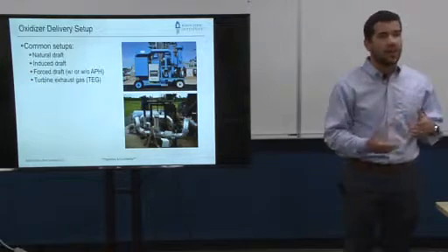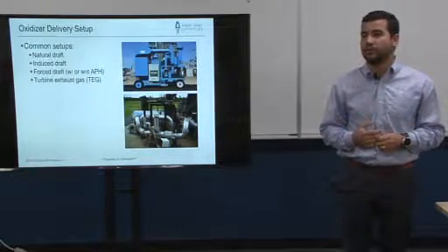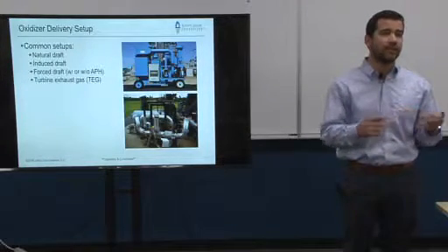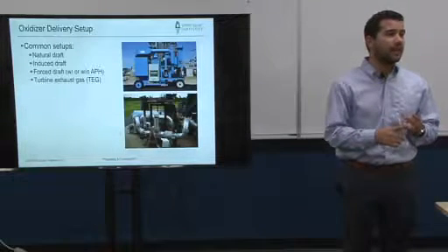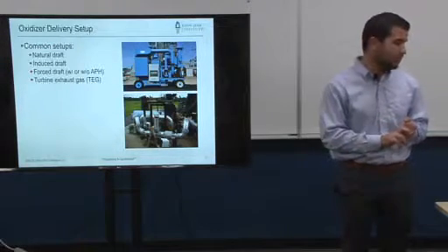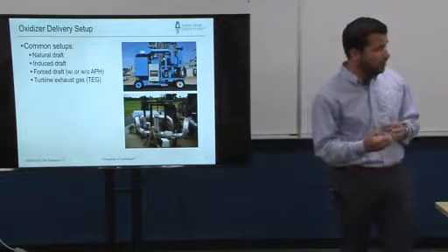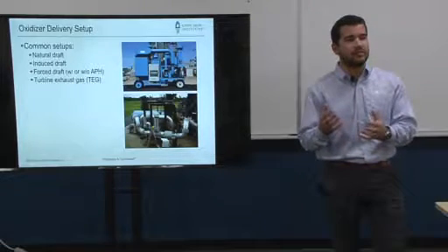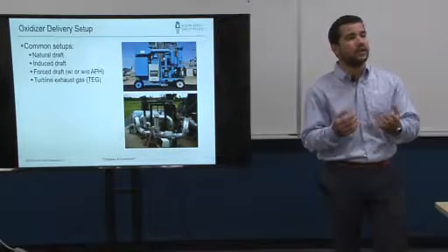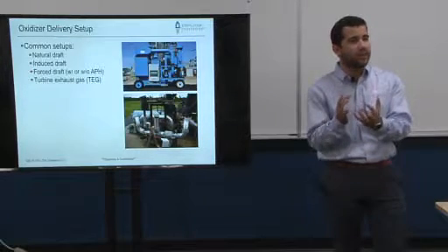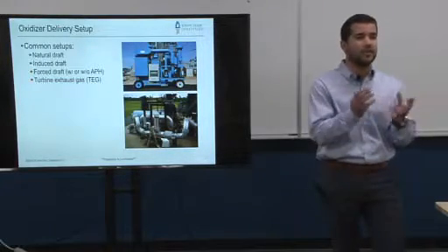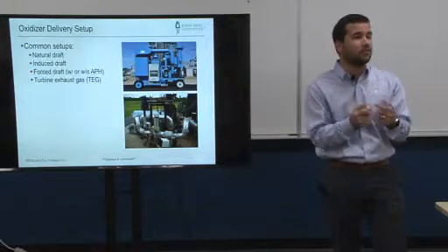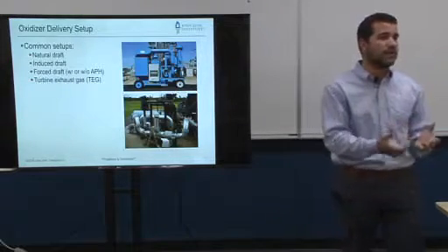And then finally, how is the oxidizer or the oxygen being delivered to the burner? We all know that in order to have combustion, you need essentially three things: fuel, air or oxygen, and an ignition source. That's how you're going to get combustion going. So depending on the heater design, you can have a natural draft burner. That means you're utilizing the buoyancy inside the heater to inspirate the air. The hot gases inside the furnace are lighter than the air outside, so they float, and when they do that, air is inspirated through an opening on the burner. That is the natural draft type.